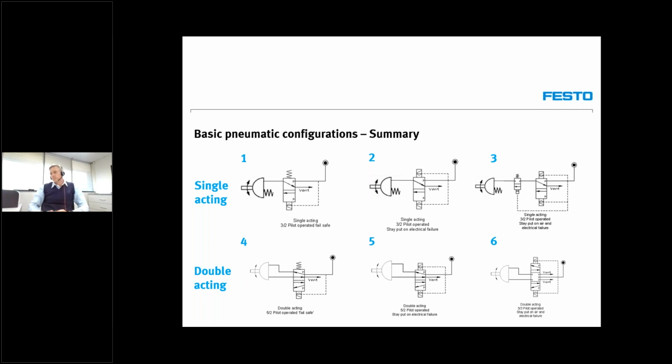So they use a combination of an air receiver, which is essentially an air volume collector, and valves in different orientations to cause that device to either open or close, or even to cycle a couple of times under a fail condition. With pneumatics, there are many ways to tackle this particular topic. Once again, understanding how pneumatic circuitry works definitely aids a person in choosing the best solution for their particular plant or application.